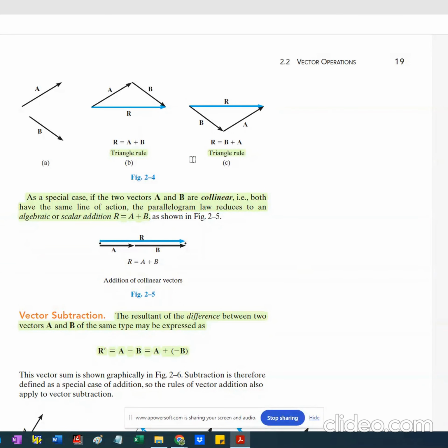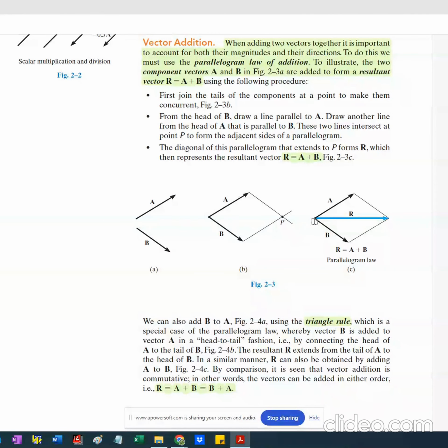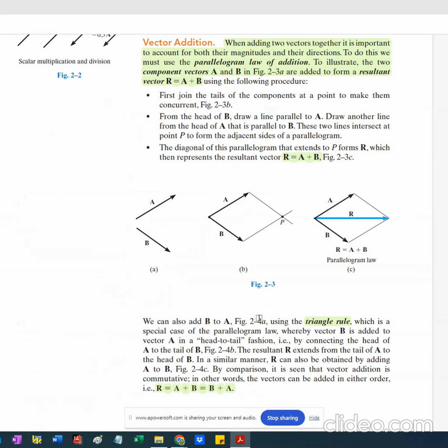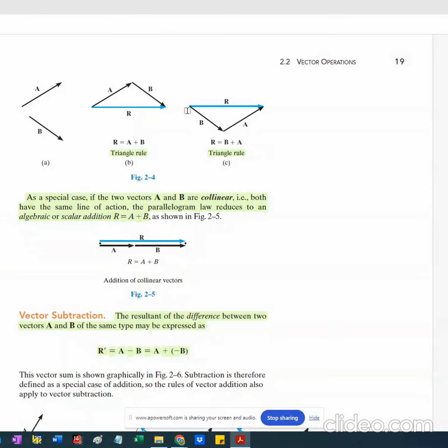Using geometry, you need to know some angles, some more information in addition to magnitude. You can then calculate the magnitude of the resultant as well as its orientation. Here it appears that the resultant is horizontal, but that doesn't mean all cases will be such. The diagonal of the parallelogram or the third side of this triangle could be other than horizontal.